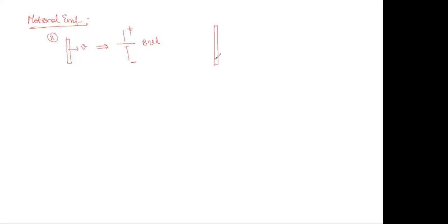Suppose the same conductor has velocity V making an angle theta here. So we can resolve this as V sin theta and V cos theta. It can become like a source once again. Obviously we are talking about the magnetic field going inside. So V sin theta into the corresponding length L. This is positive, negative. So the perpendicular component will contribute to the EMF in the rod. V cos theta does not contribute here.